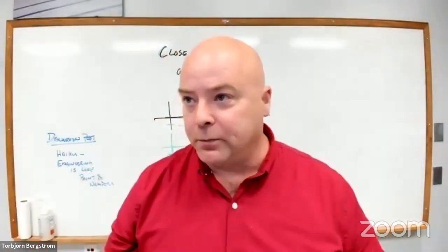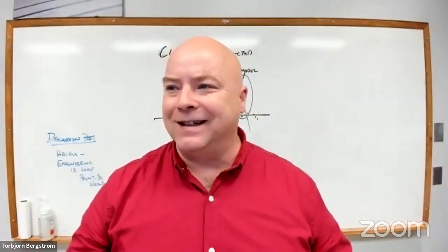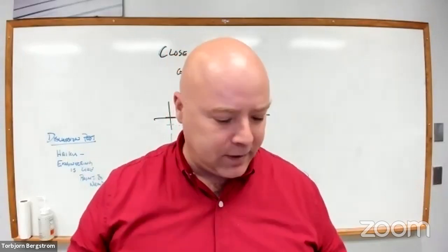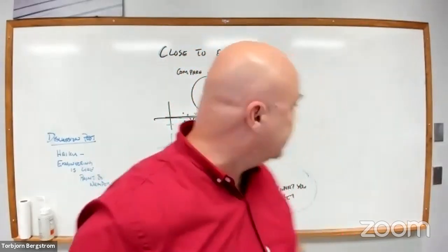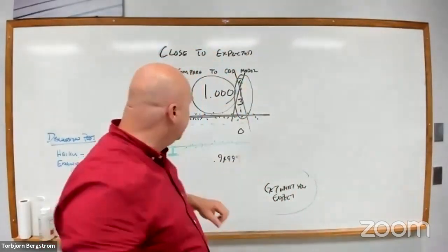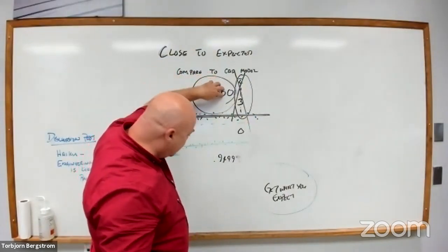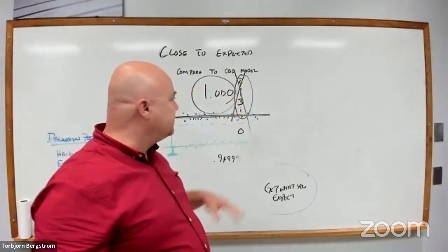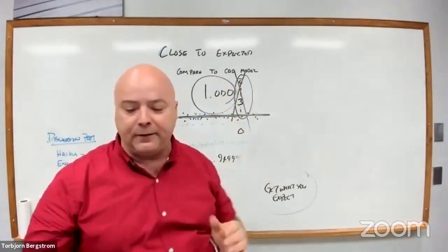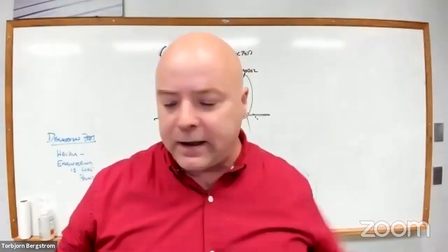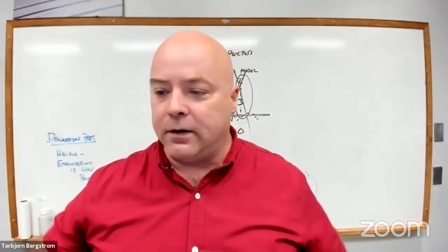I wanted to use the word precision the way people use it in layman's terms, but it's not the right word here, because precision is how close these numbers are to each other. Accuracy is how close this is to the true value, and resolution is how many decimal places we have. So if we reduce our resolution, we can increase our certainty or decrease our uncertainty.